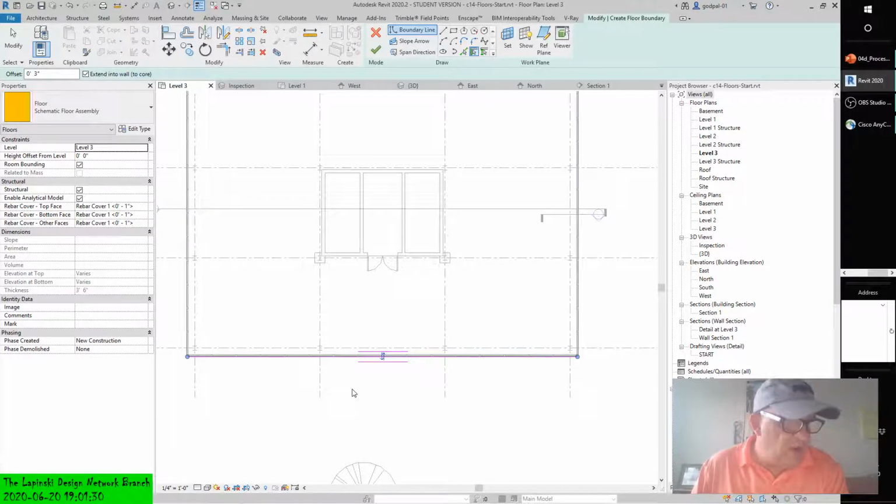So, begin by picking the exterior curtain walls north or south. I selected the south. The first one you pick will determine the span direction of the structural floor. You can change this at any time by picking the span direction tool from the draw panel and then selecting one of the boundary lines in the floor sketch. And we can do that.